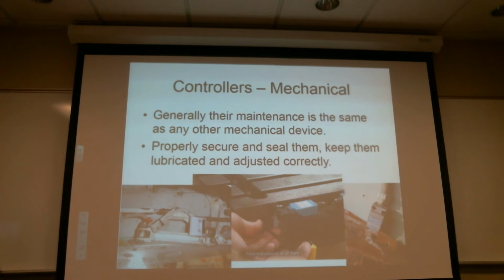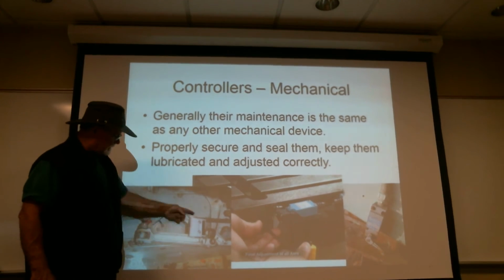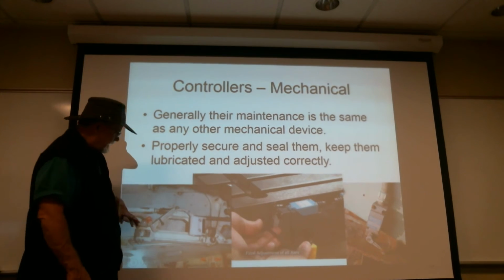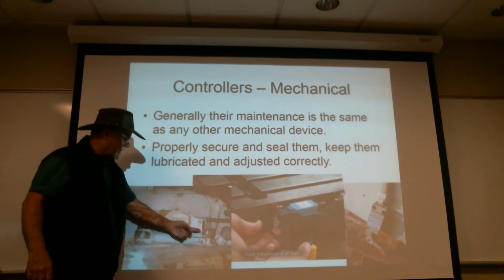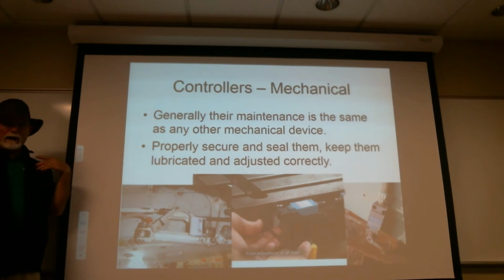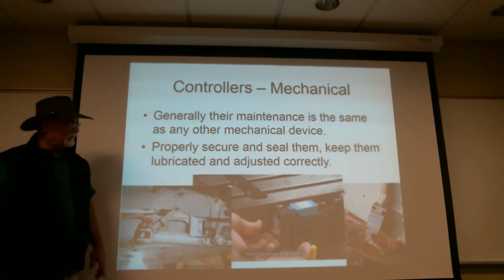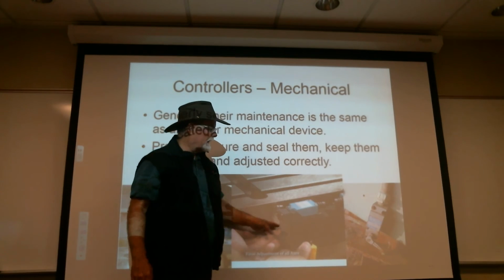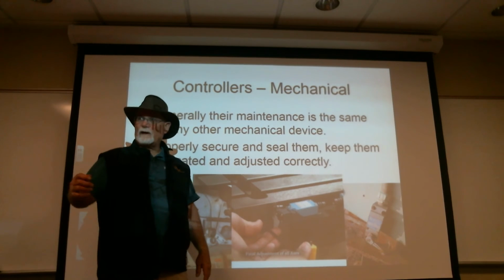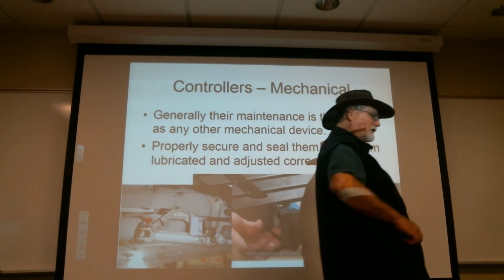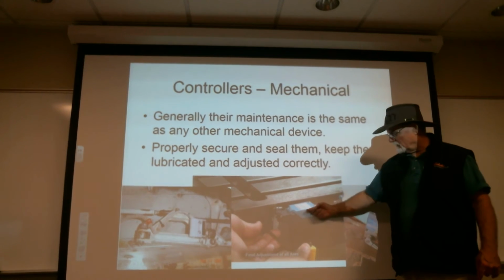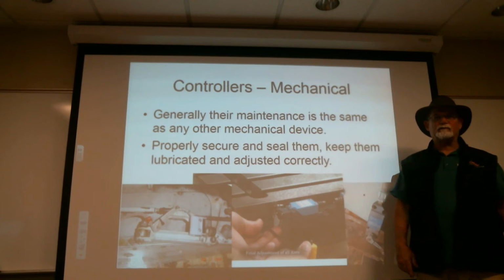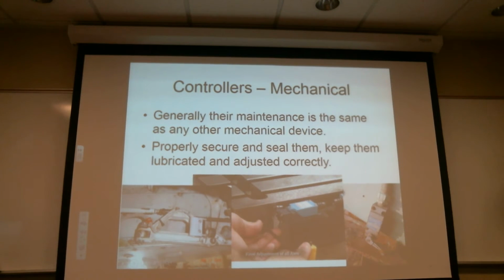So a few examples. There looks like a gear door limit switch here, sort of comes up like this and then sits right there. And as that comes up, it closes the limit switch and tells it it's either up or down. Don't really know. This one here actually is the X travel on a mill. So as I engage the drive, it starts going and cutting its way, winding its way along until it gets to there, and then it disconnects. Okay, it shuts the motor down.